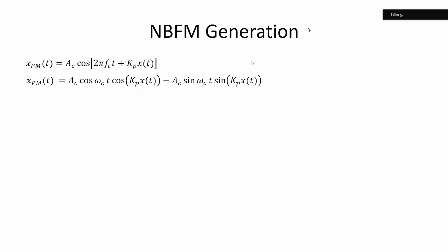Okay. So those are the practical points, because you need to get a license from the government in any country in order to transmit RF. That license is normally very strict. They will specify that your center frequency should be this, your stability should be within this limit, and your guard band should be like this. So all that is specified, and for that license you'll have to pay, and you will have to adhere to it.